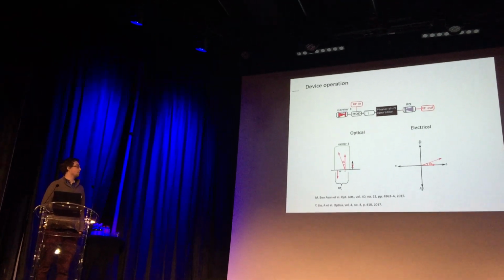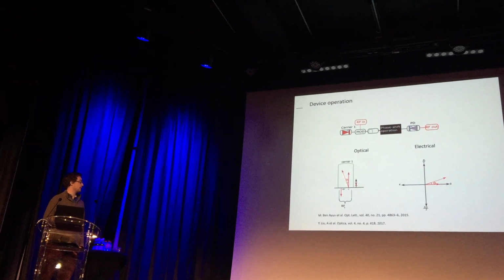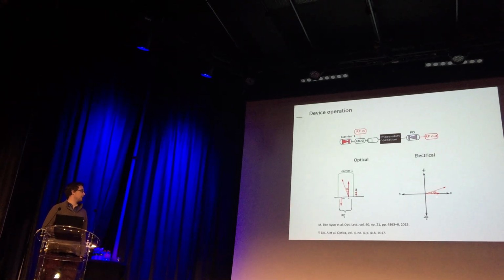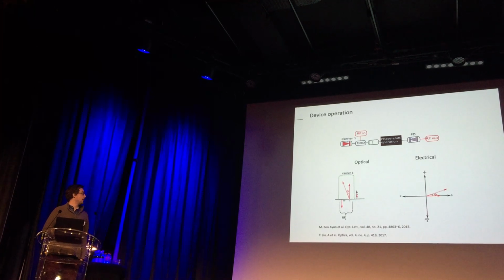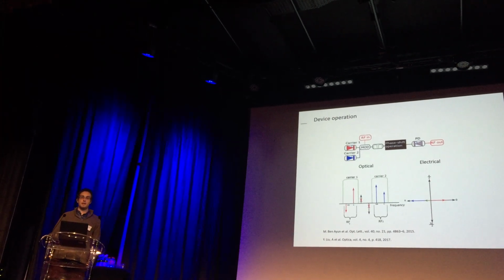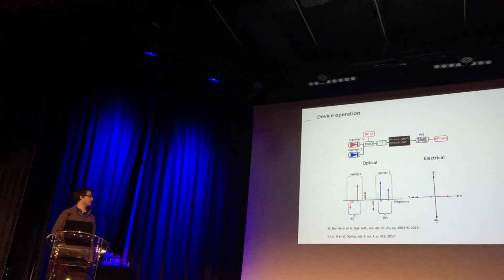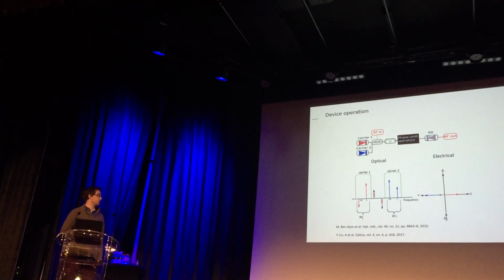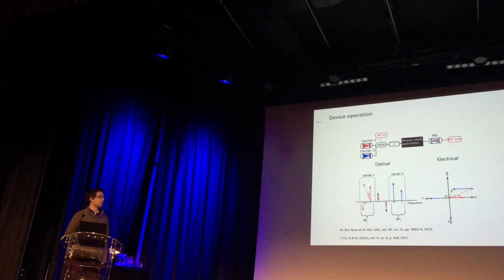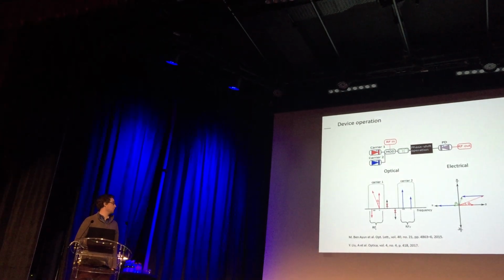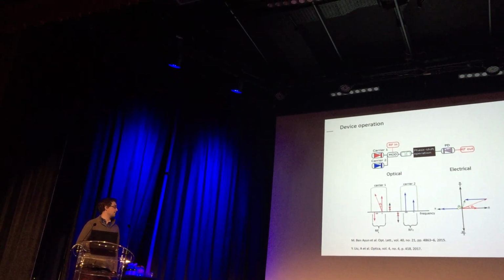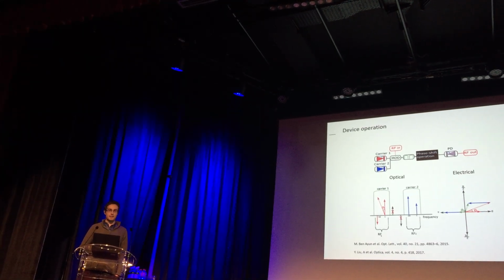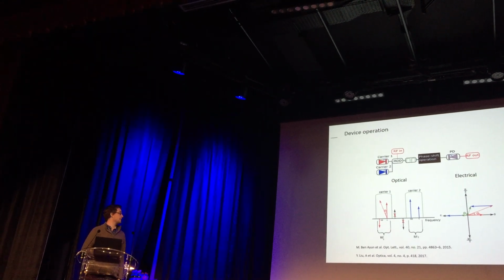And if we turn on the pump, this generates a phase shift here, and this induces a phase shift on the output RF tone. But now we add the second carrier, which is 180 degrees out of phase. So you can see the resultants here, which is this small green one, and it's pointing in the opposite direction. And now, if we apply the same phase shift as we did a few moments ago, we can see here that the phase θ2 is much larger than θ1. And this is the core idea of our phase enhancement scheme.